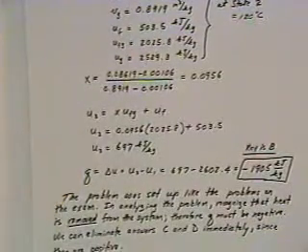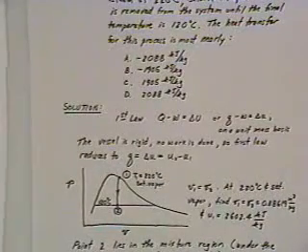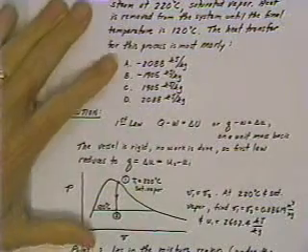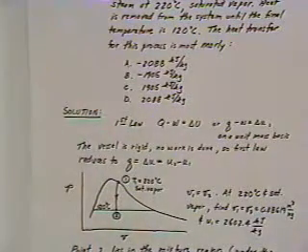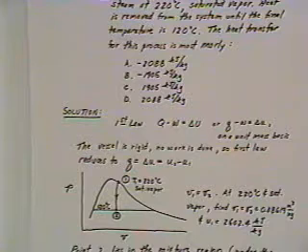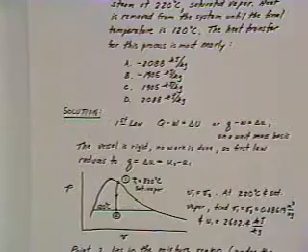Now if we go back to the original formulation of the problem, I'd like to discuss that for just a minute. In setting up the problem, two of the answers were positive and two were negative. If we look at what's happening in the system, we've got a rigid pressure vessel originally at 220 degrees C. The heat is removed until the final temperature is 120 degrees C. Heat is removed from the system, so by our sign convention the heat transfer must be negative.